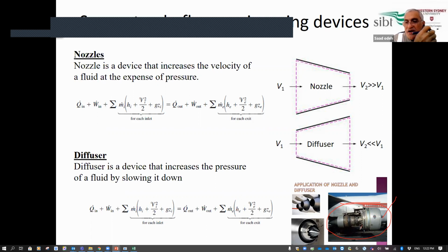So the air under high pressure with the fuel will mix together in a combustion chamber to produce heat. The amount of heat with high pressure will rotate the turbine. So you need high pressure to make more energy to rotate the turbines of the engine. And that's why we are using a diffuser at the inlet.